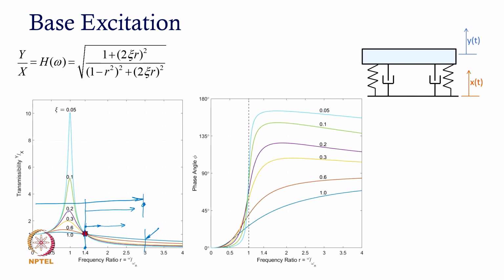Okay. So, let us say if I do not want the rider to get large amplitudes, maybe I will choose zeta equal to 0.2 or so, or maybe 0.3 or so. So, I will definitely get double the amplitude at resonance. Look at what happens in the post 1.4 value. If I do not have damping, or have a very reasonably small level of damping, this light blue color curve shows that I get a fantastic attenuation, much lower vibration response, right.